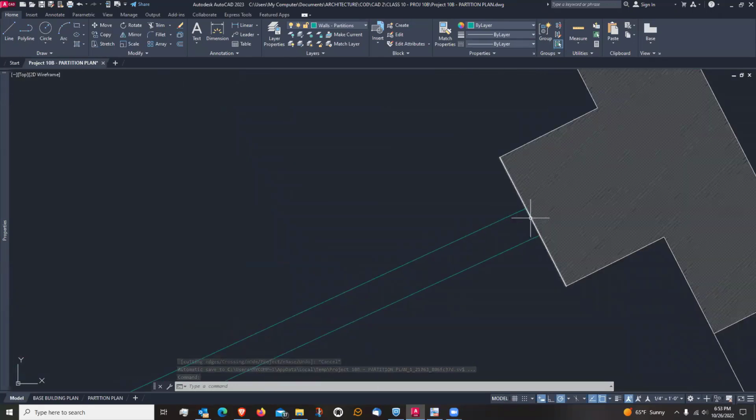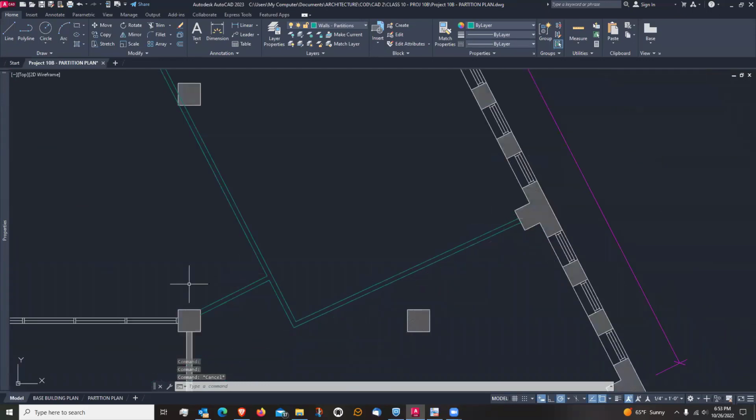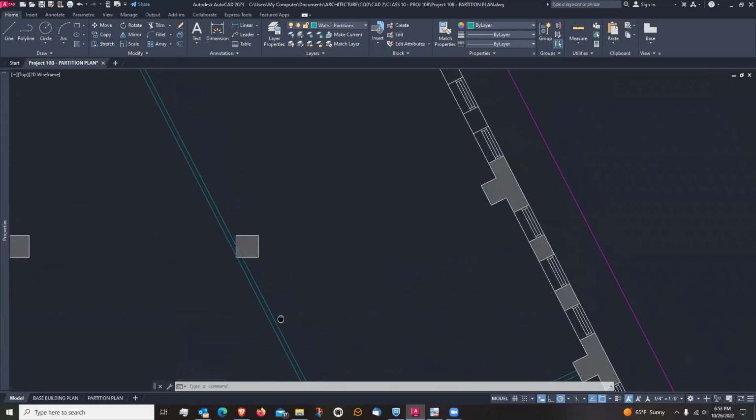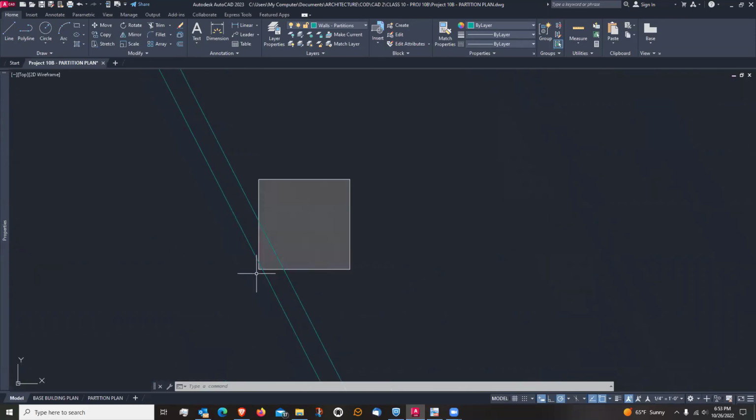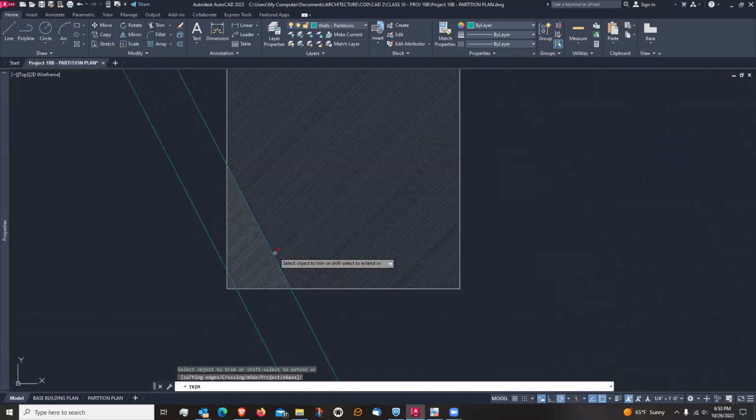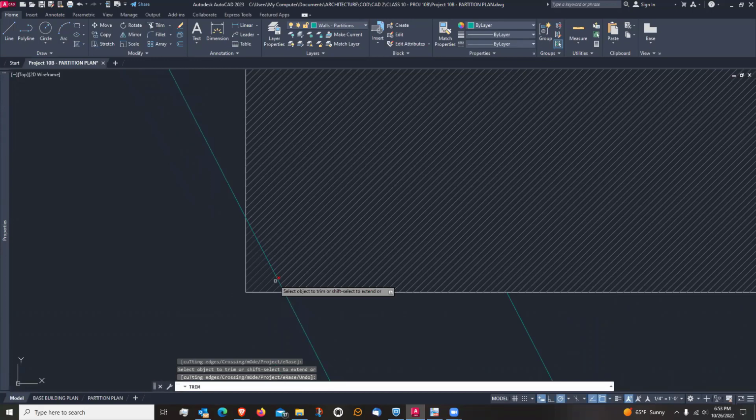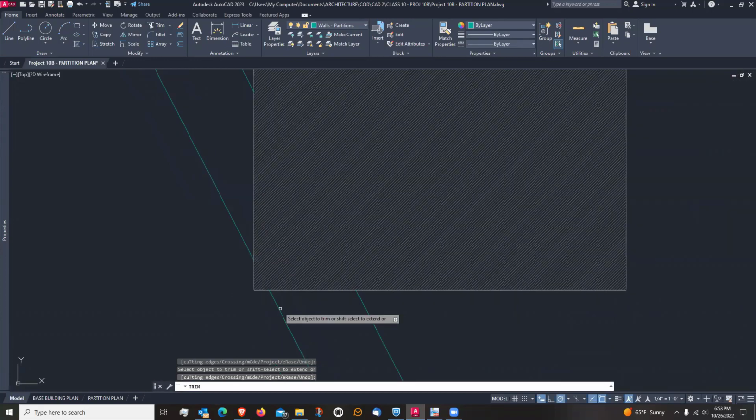So when I have my exterior wall and my demising partitions, I leave that. I don't trim this here, but just amongst the partitions, that is what I would trim. Oh, this is awkward, but I'm going to leave it. That's just what was there, but I will trim out, because the partition doesn't actually go through the column, it butts up to the column.